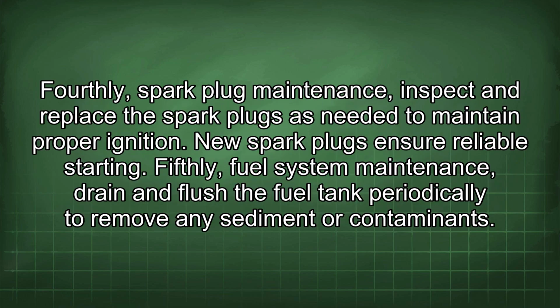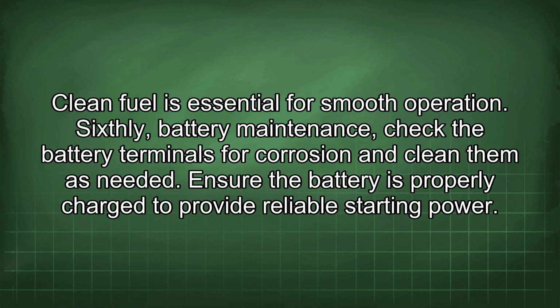Fourthly, spark plug maintenance. Inspect and replace the spark plugs as needed to maintain proper ignition. New spark plugs ensure reliable starting. Fifthly, fuel system maintenance. Drain and flush the fuel tank periodically to remove any sediment or contaminants. Clean fuel is essential for smooth operation. Sixthly, battery maintenance. Check the battery terminals for corrosion and clean them as needed. Ensure the battery is properly charged to provide reliable starting power.